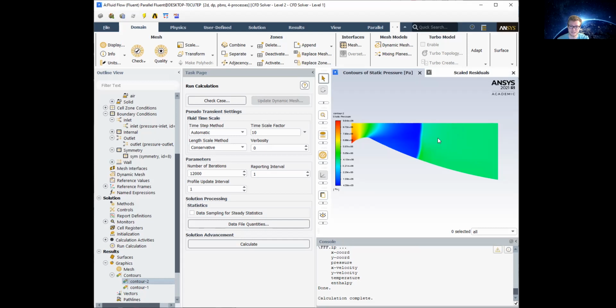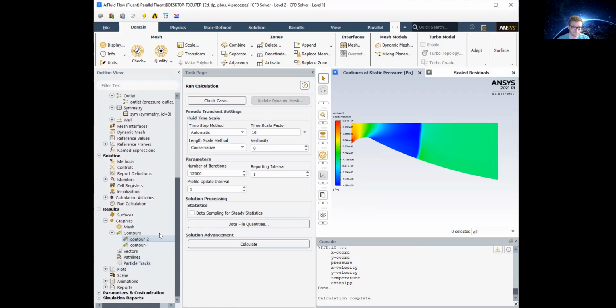That, and if you use the pressure tables, or the shock wave conversion for a normal shock wave, you can calculate an approximation for the amount of pressure drop and temperature drop and velocity drop, along with Mach number. So once you hit this giant, what's it called? Shock wave, I'm so sorry, you're going to have a huge drop right there.